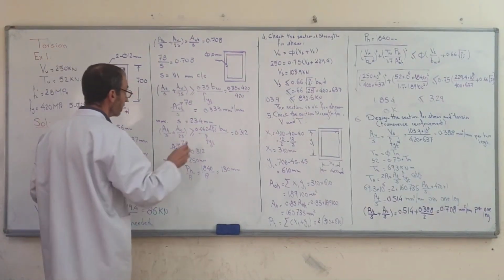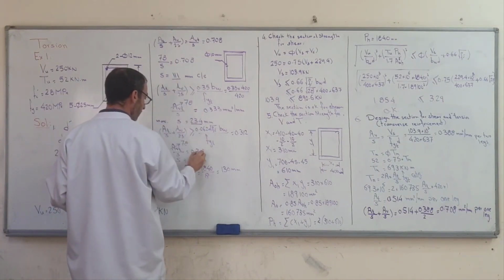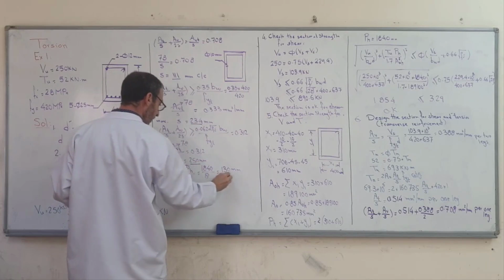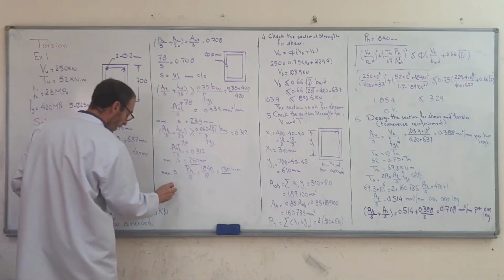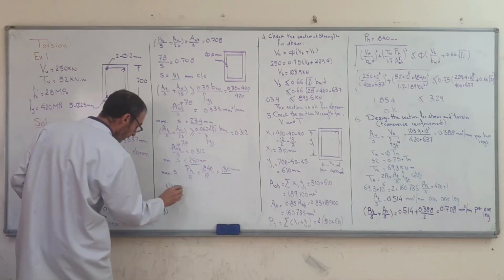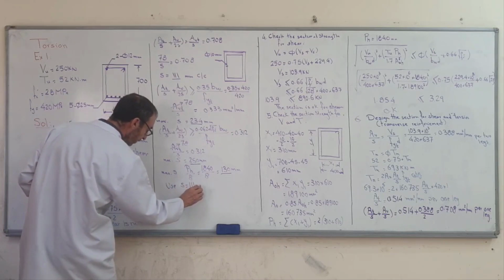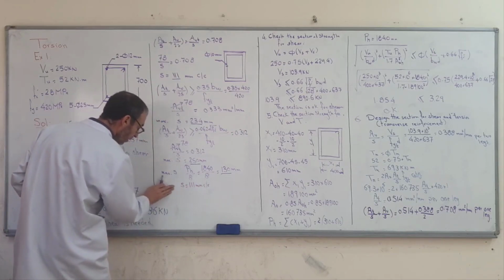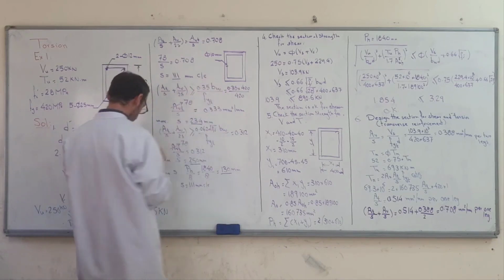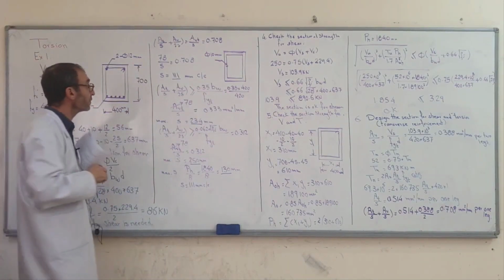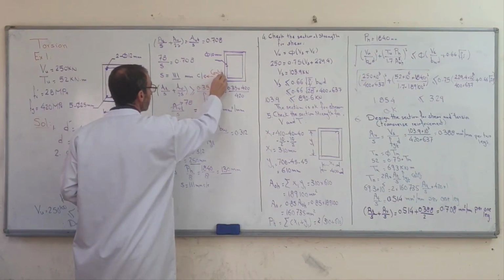Now we found this distance from the loads, and this one from the minimum requirement. Then we use the lesser value. So S is equal to 111 millimeters center to center. This is the controlling, or governing, value.